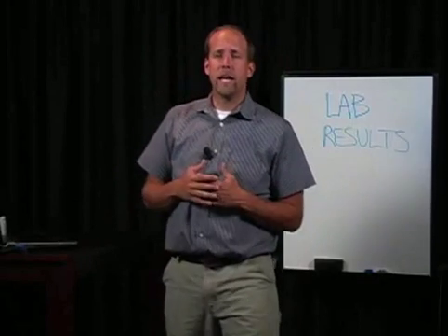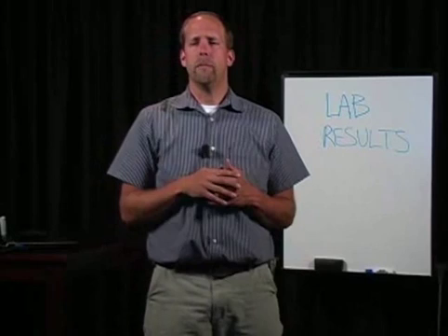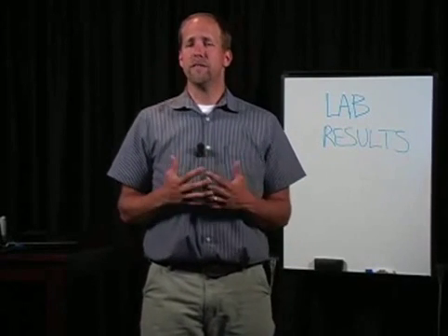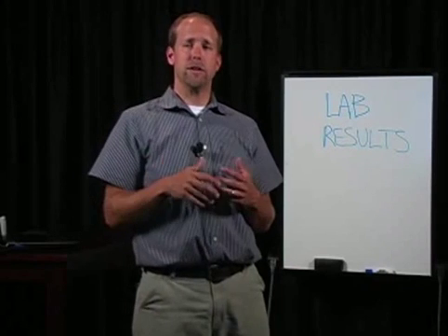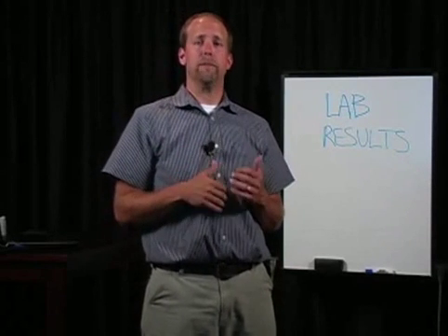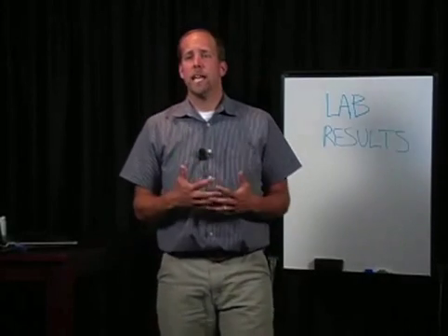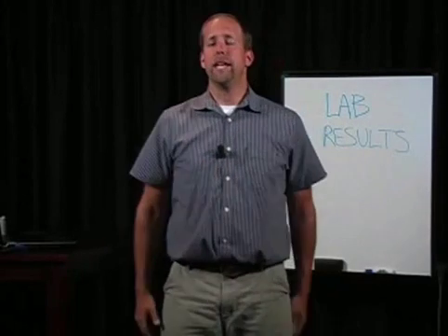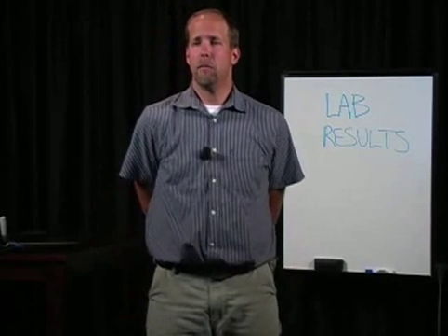During a flood cleanup, the indoor air quality in the home may appear to be the least of your problems. However, failure to remove contaminated materials and reduce moisture and humidity can present serious long-term health effects and risks. Standing water and wet materials are a breeding ground for microorganisms such as viruses, bacteria, mold.